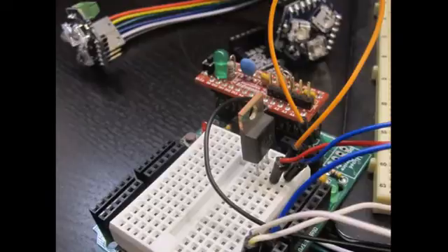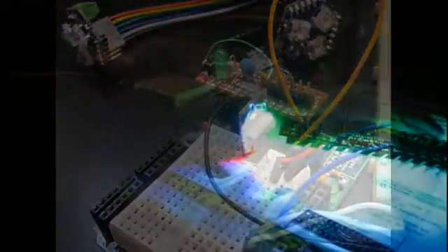Because the Megabrites take a lot of juice and a higher voltage, I set up the Arduino on a protoboard, powered the Megabrite with a 9-volt supply, and put in a 7805 voltage regulator to feed a nice and safe 5V to the Arduino. The second demonstration includes the output to the serial monitor, so in that case I powered the Arduino from the USB port and kept the Megabrite supply separate.